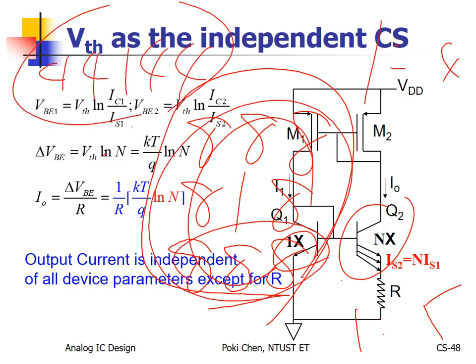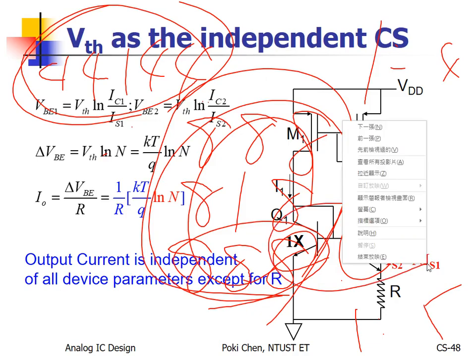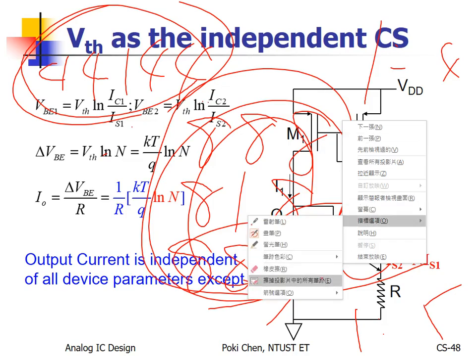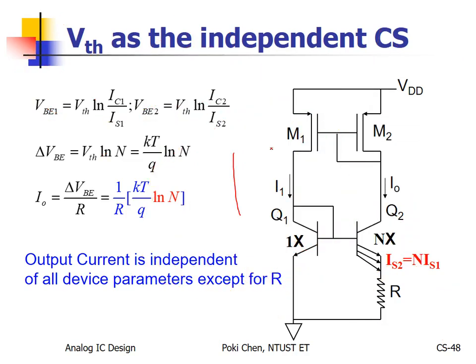But this one is 2-dimensional common centroid. It is better than this, 1-dimensional. Okay? The more symmetry, the better. And this is the reason why, if you look at the voltage reference paper, reference current paper, usually if they have such kind of BJTs, 1 to 8 is some kind of common sense. But what? You need to know.